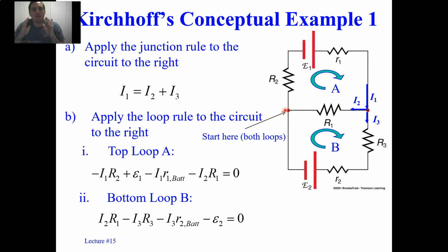Now, by the way, people have often asked me many questions about this, so let me try to clarify those from the get-go. Can you start in any corner or in any place of this circuit? Sure you can, okay? As long as you're careful. Secondly, you can't really start in the middle of a resistor or the middle of a battery. You probably should start on a piece of wire where everything on that piece of wire is at the same potential, at the same voltage. So that way you're consistent.